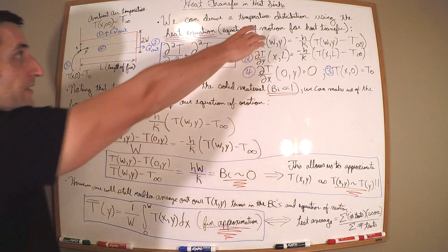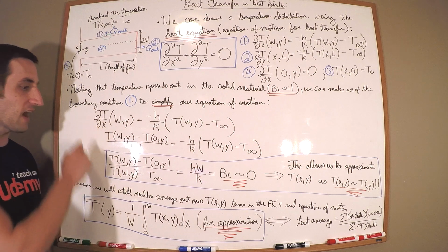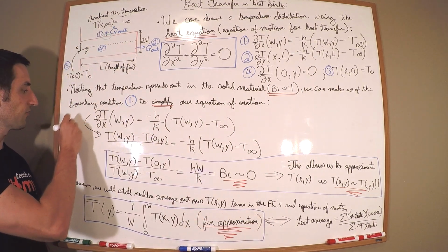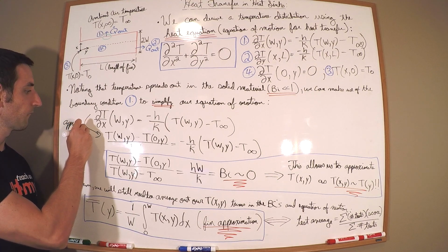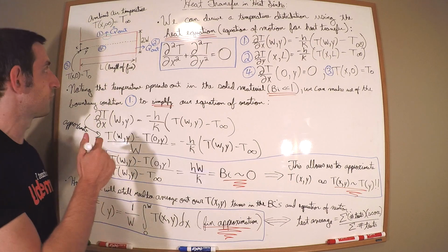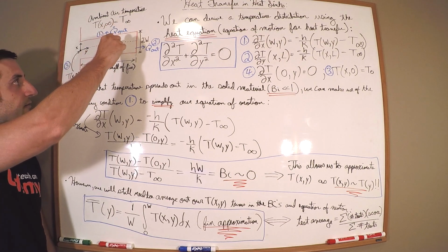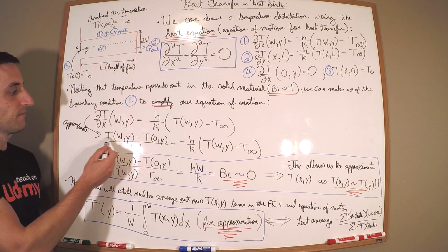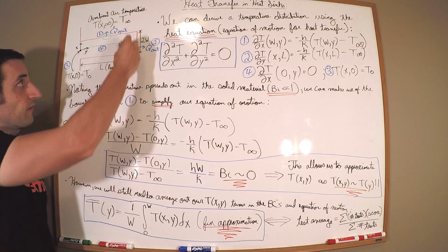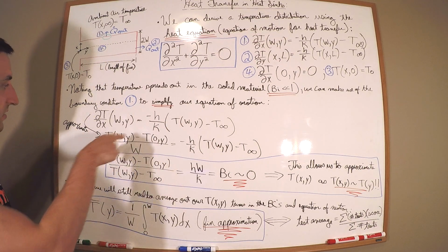equal to the following. If we take that, pop it down here, what we can do is approximate this. So from here to here, we're going to approximate the derivative of the temperature distribution with respect to x as follows. We're going to say, okay, if we're moving in the x direction, let's take the temperature here minus the temperature here, divided by the x distance. T_W up here minus T_0 down there. We traverse a distance x, or rather w, in the x direction,